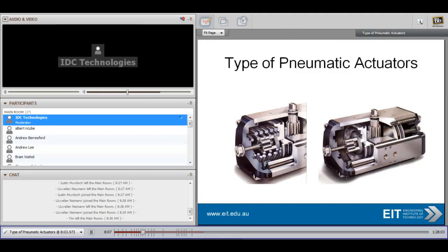We're going to find that they give us a constant high torque. They have minimum hysteresis losses. The stroking speed is relatively high, and they are easy to put together, to assemble, to do the maintenance. You can see where the rack and pinion actually comes in on the inside, whereas that rotates, so we're going to get the actuator to open or close, and that's going to operate the valve.